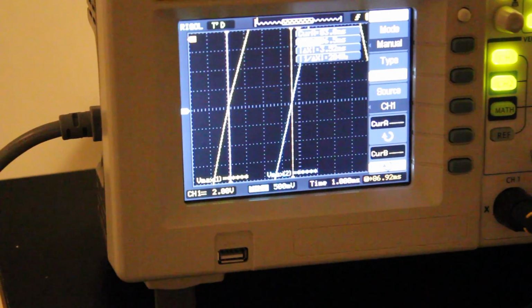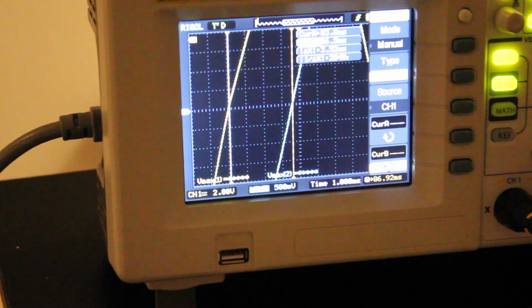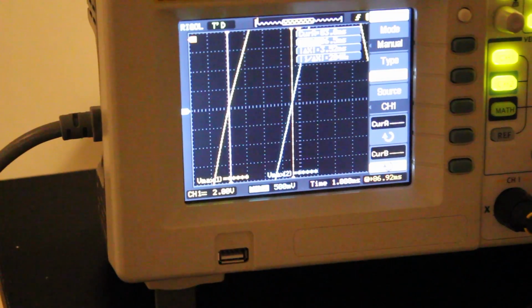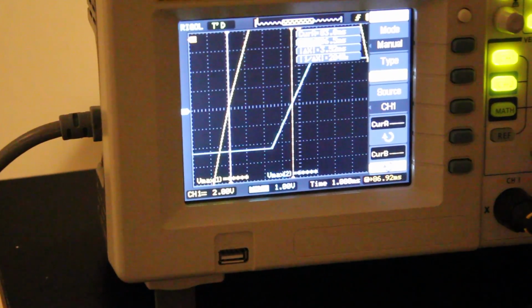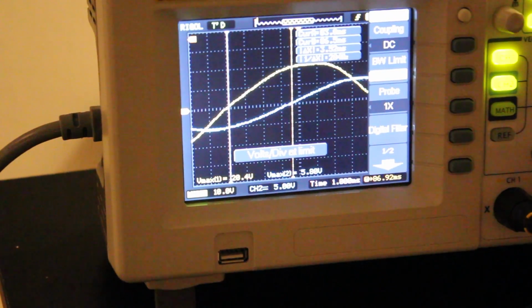So I forget what the cutoff frequency was. If we put something closer to 15 hertz on here, then we would have seen that. So we're at 60 hertz, putting it through a 15 hertz cutoff, low pass filter. So anything under 15 hertz is going to pass. And that is a low pass filter. So now, you can apply this. Sorry, I'm totally distracted by the scope here.